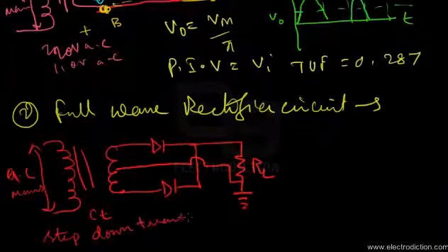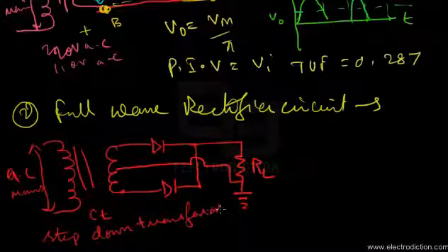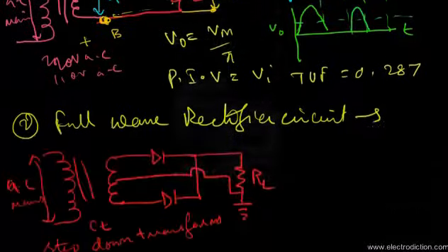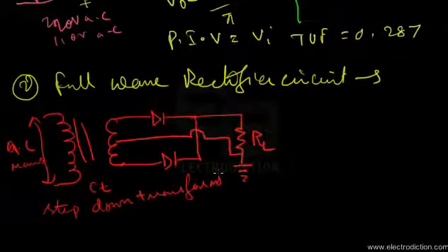Okay, so it is a little bit different from the two terminal transformer used in case of the half wave rectifier circuit, in that it has three output terminals on its secondary. Now the voltage at the center tap of the step down transformer is fixed at 0 volts, that is the ground voltage.